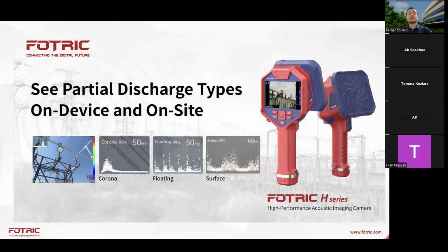Okay, now let's talk about how to stop guessing the type of partial discharge. You really know and understand that an acoustic camera prevents you from guessing where the problem is. But even other acoustic cameras that are out in the market can do that. But you take a picture and you only find out if what you saw in that transmission line, distribution line, or electrical enclosure was an actual partial discharge or if it was corona, tracking, and arcing.